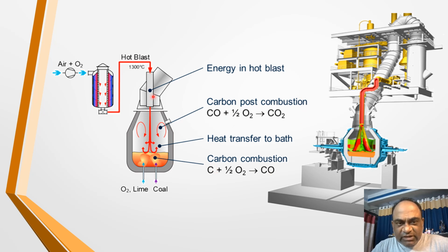In the process, they are collected and put into the gas holder. They have a certain calorific value, which is why they are collected and kept in the gas holder for further use in different processes. We have many furnaces at different places where the rolling mills are working, and in those furnaces, these gases are used for further heating the slabs or the billets or anything like that.